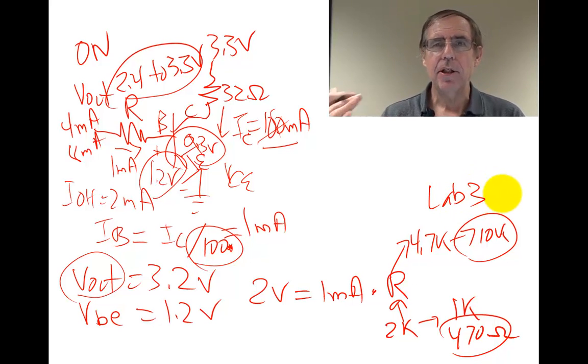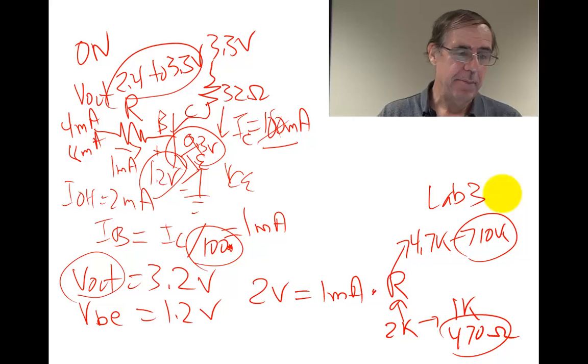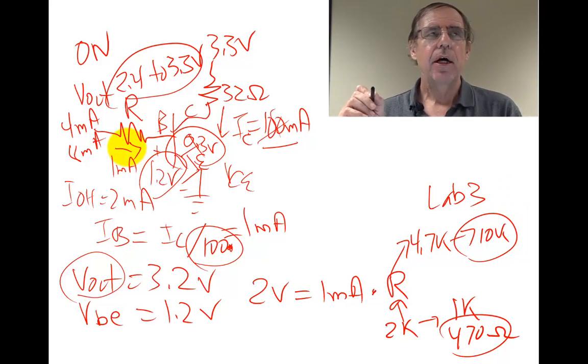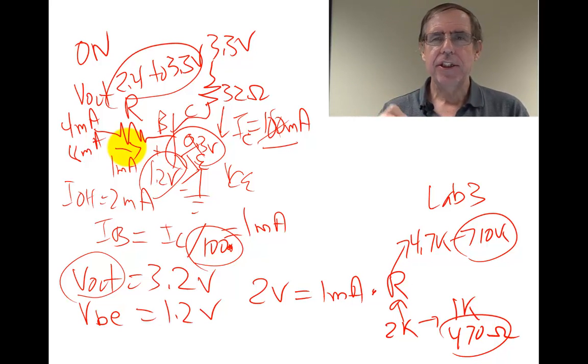To make the alarm clock sound, we're actually going to make this resistor bigger than what it would take to go into saturation so that the speaker isn't too loud.